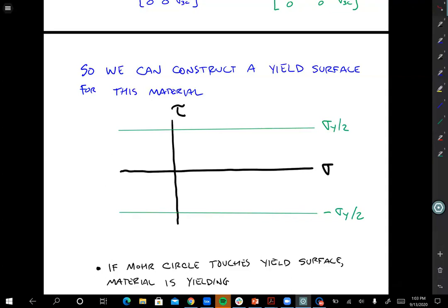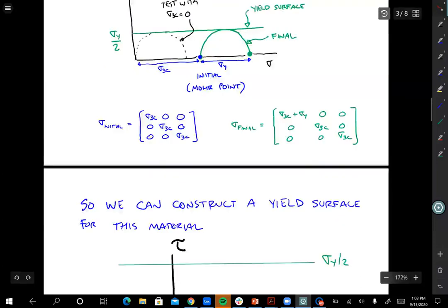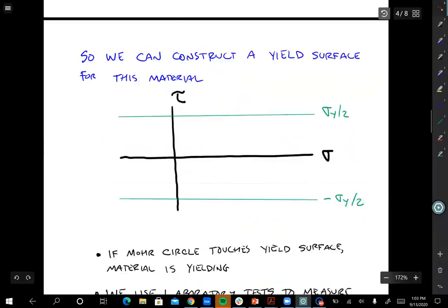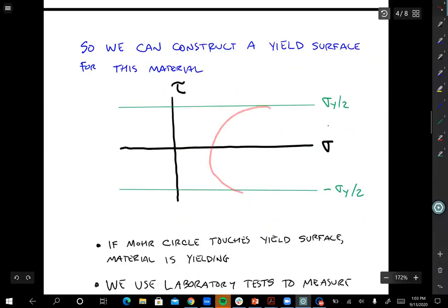Okay, so if you took that bar and did compression instead of tension, it would have the same strength in both directions. So up here I was only drawing half the Mohr circle. The full Mohr circle would actually go, whoops, let me try that again. It would actually go tangent to both lines, just like that, right? So that's the actual yield surface. It involves two lines.